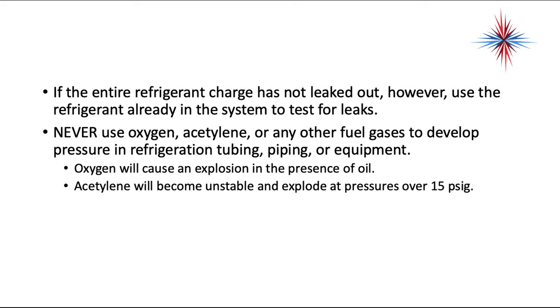Never use oxygen, acetylene, or any other fuel gases to develop pressure in refrigeration tubing, piping, or equipment. Oxygen will cause an explosion in the presence of oil. Acetylene will become unstable and explode at pressures over 15 psi.